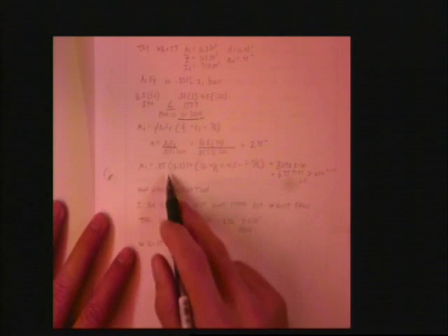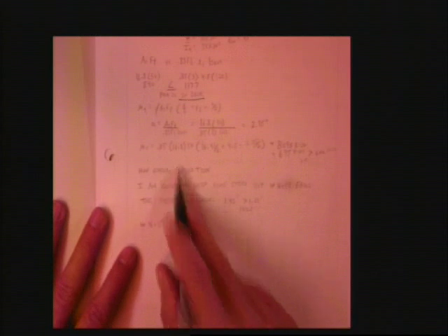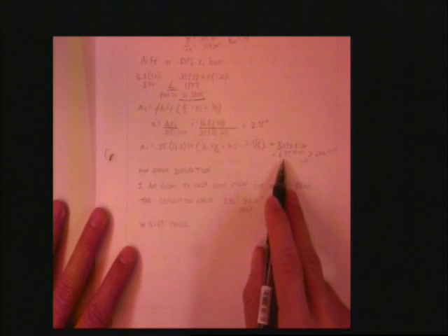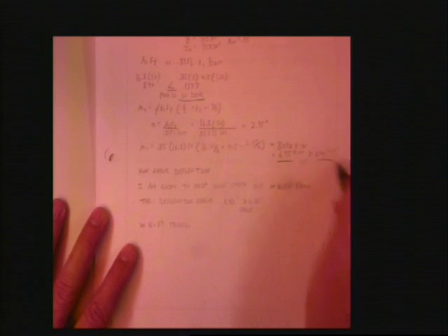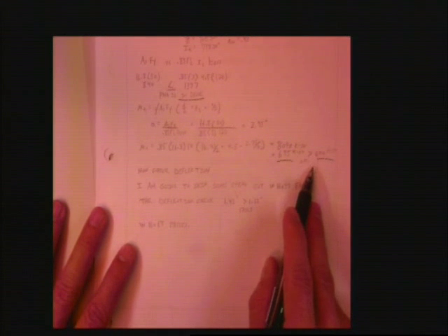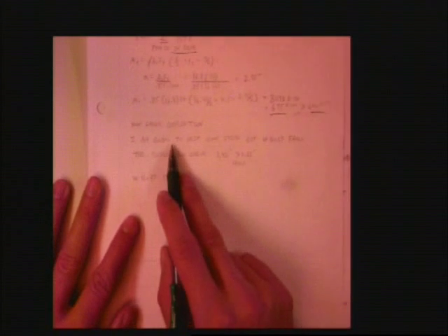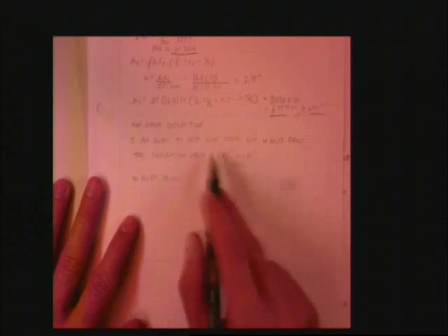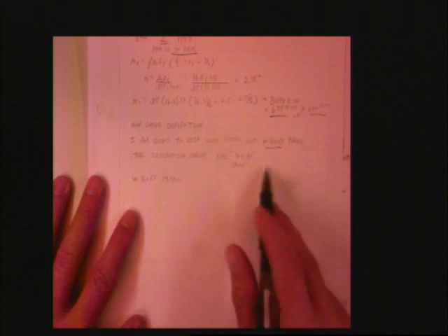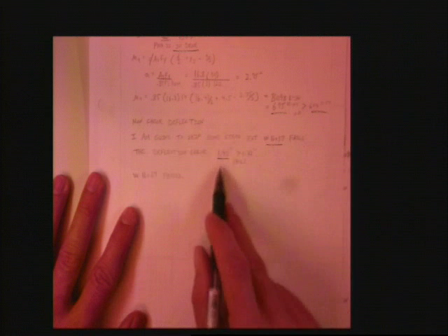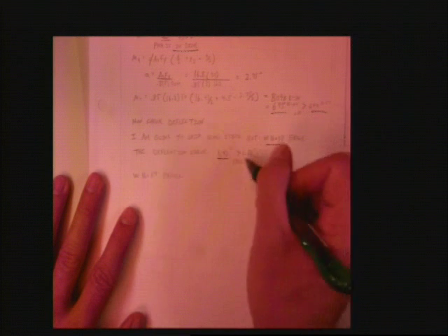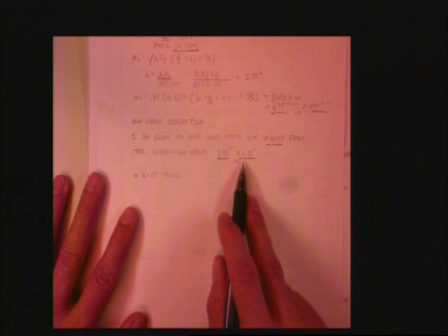Great. If we get our A, plug into our canned equation, we get 675 kip feet, which is pretty awesome, man. 10% over design. That's really good. Just considering that I got there with a 1-line calculation. Okay? Now it's so sad, though, when I check deflection, which I'm not going to show you, I skipped some steps, but this W16 by 57 doesn't work. The deflection is 1.42 instead of 1.33. Fails my deflection limit.